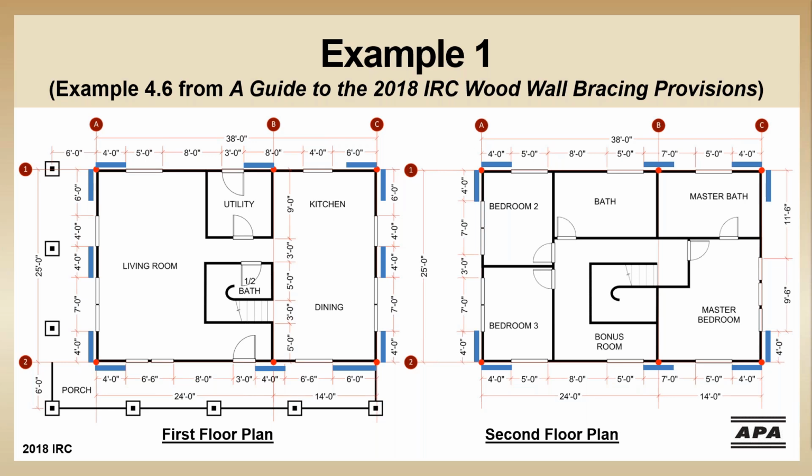So this eliminated the interior braced wall line at the upper story without changing the exterior braced wall panels at all. So these look exactly the same whether you incorporated braced wall line B or not. But at the lower story, we ended up shifting that interior wall bracing to the exterior walls. So you have a little bit more bracing at these exterior walls.